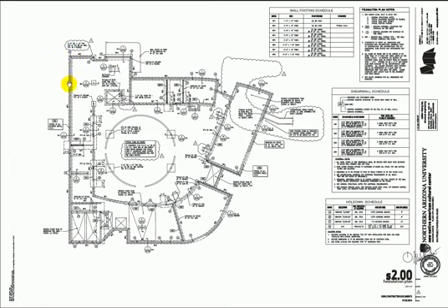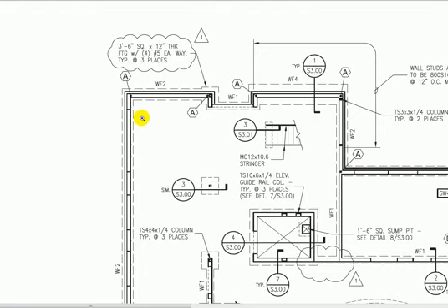But what I see here looks like we have some sort of bearing walls around the building, around the whole perimeter, sitting on concrete footings, and I'm seeing a lot of things here. Let's zoom into a corner and see what we can see. These little bubbles around things are revisions that were made with a little 1, so that ties it to something that was revised after the first issue of the drawing.